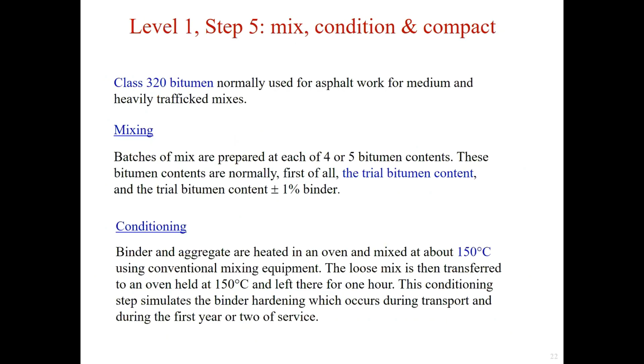Once the trial binder content is chosen, we start to mix and then condition and compact the asphalt mix in step 5. We need to ensure the sample prepared in the lab have properties as close as possible to asphalt placed in the road, and this is an important aim of asphalt mix design procedure.